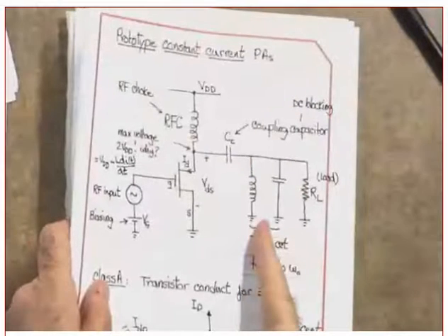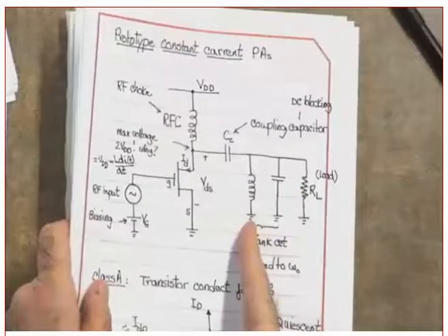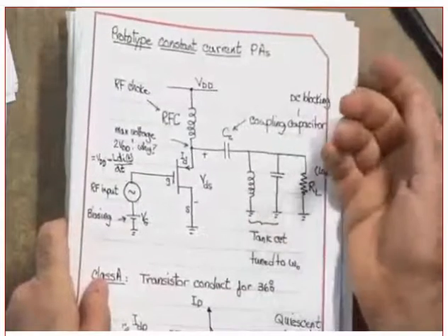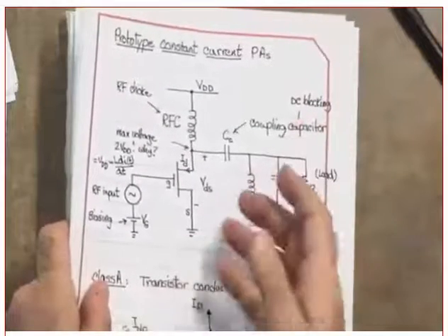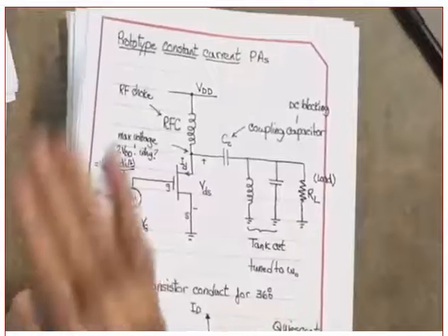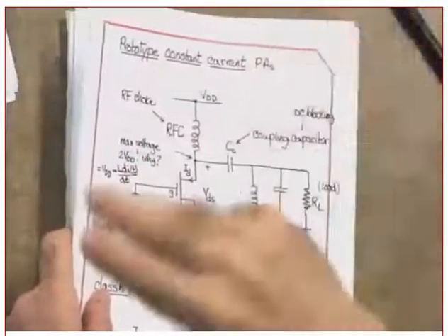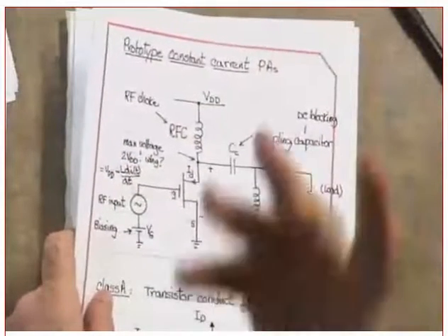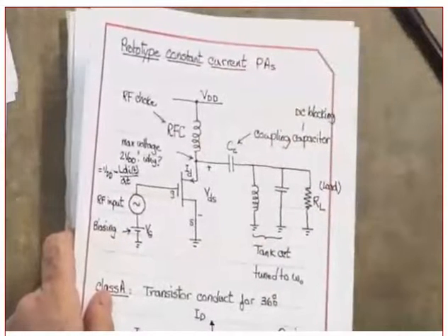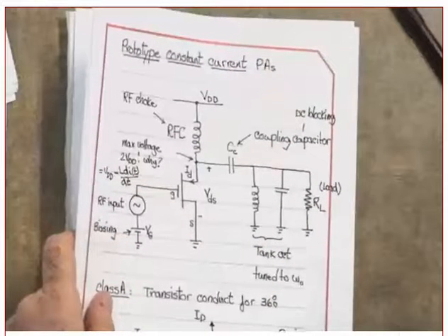What is it equal to, by the way? 1 over square root of LC. You follow me or not? But that's just one frequency. Did you get this or not? I want the behavior of this to be very close, in other words, to present a very small impedance or very high admittance. Admittance is the opposite of impedance. Very high admittance at the harmonics. Did you get my point or not?